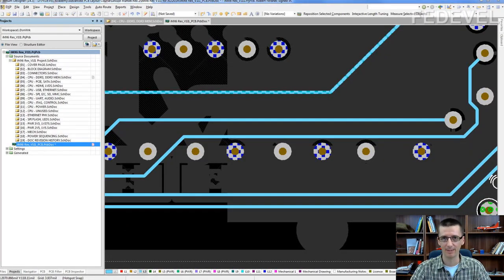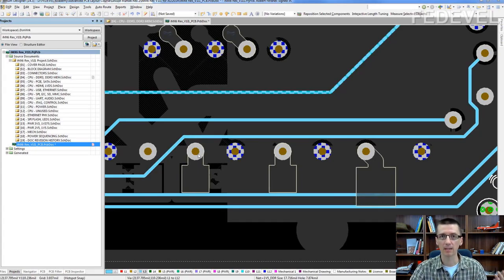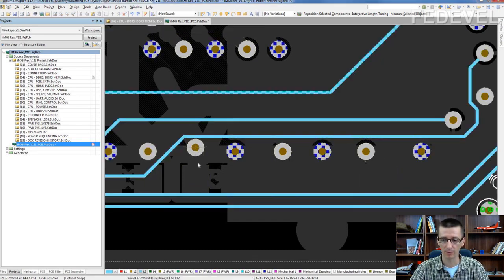Small tip. If during phase 2 you need to move some tracks or wires and you get a violation, then clear it immediately. For example, if I move this wire and I see a violation here, during phase 1 you can safely ignore it. It's not a problem. During phase 1 in this area you will probably be redrawing these tracks many times. So in phase 1 it is really enough if you fix this violation by the end of the phase.